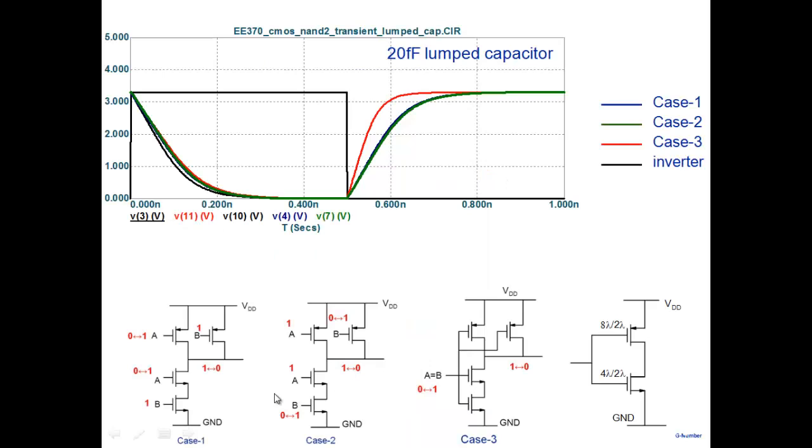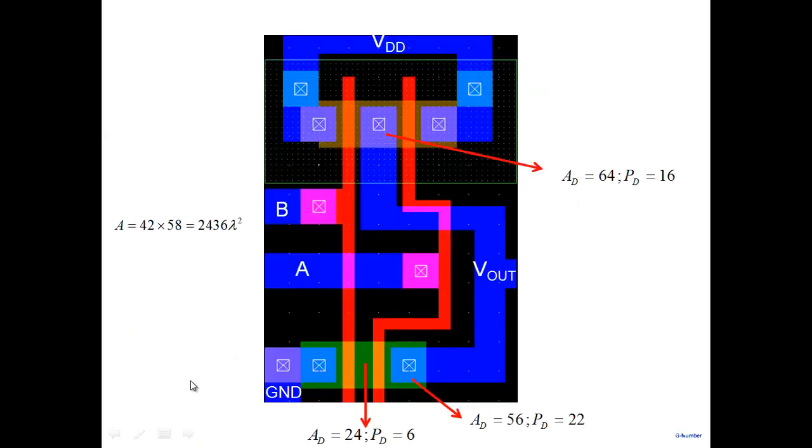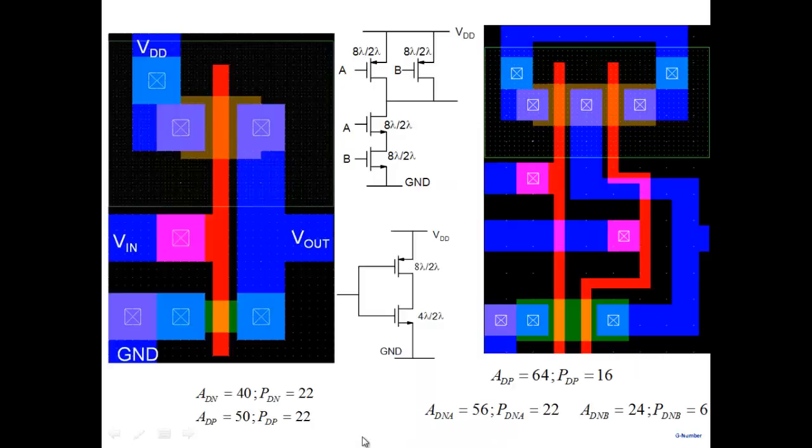Note that in this area, the source and the drain are shared together by the two NMOSes, okay? So this happens to be the drain of the lower transistor, and this also happens to be the source of the upper transistor here. So this entire area is needed for drain to body or source to body capacitance here. So once you do the layout, you have these three relevant areas, which can then be used to estimate the capacitance here.